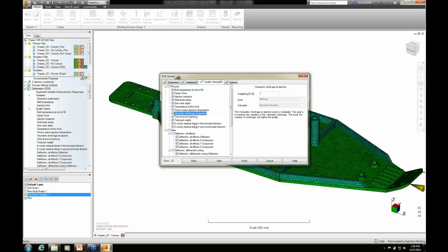On the flip side to that, I had a company just recently that was trying to manufacture a component that had a series of holes in it, and they were trying to control the location of a weld line. In their particular case, the filling criteria was much more important than anything else. So they were looking at the ability to fill, the total part weight. Those were the ones they weighted heavier, and they kind of ignored warpage. So you'll weight these heavier all based on the criteria of your part, so that as you're defining and simulating your part, the goals are given the most appropriate weighting.